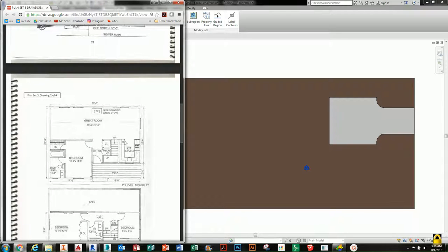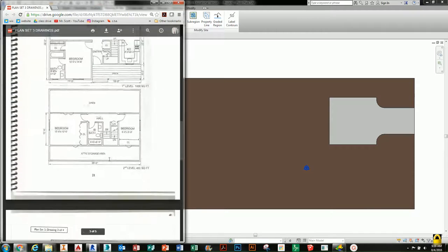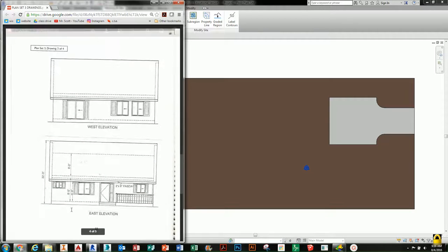However, you've got to keep in mind, before we start drawing these floors, we need to know our levels. And as we discussed in class, our levels are going to be 0, 0 for the site. We have 2 stairs, right, which could be considered as 6 inches each or 7 inches. So you can make that 1 foot or you can make it 14 inches. But I'm just going to go with 1 foot. So we've got level 1, 0, or site 0, level 1, 1 foot. Level 2, the second floor, is going to be 8 feet plus the thickness of a floor. So we'll go level 2, 9 feet, and finally our roof is 22 feet 3.